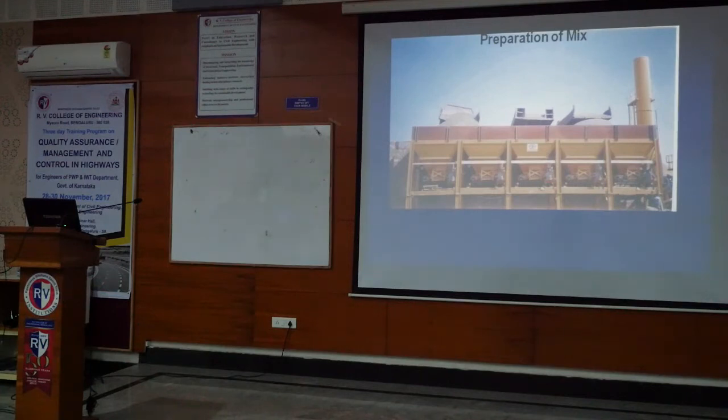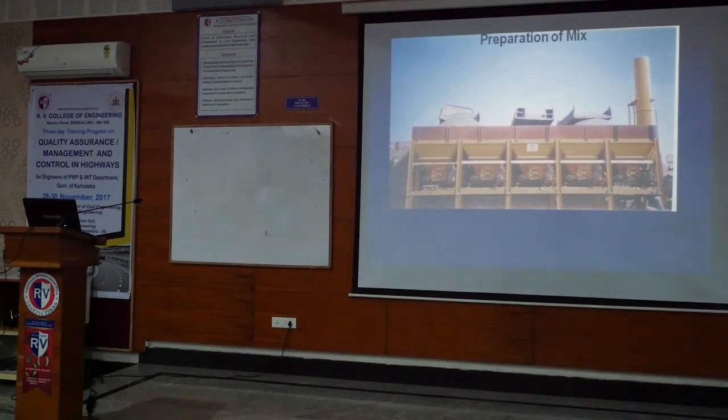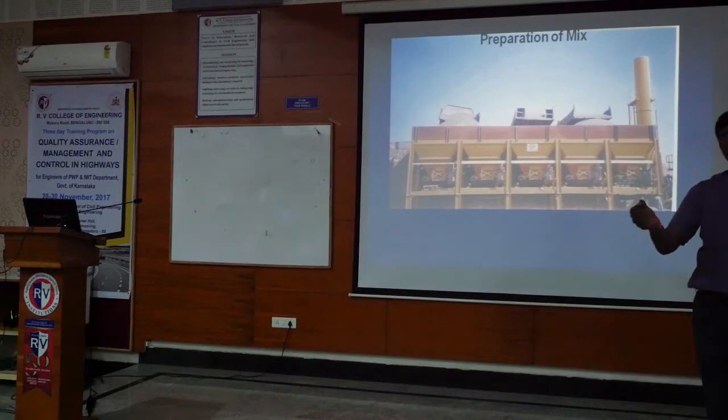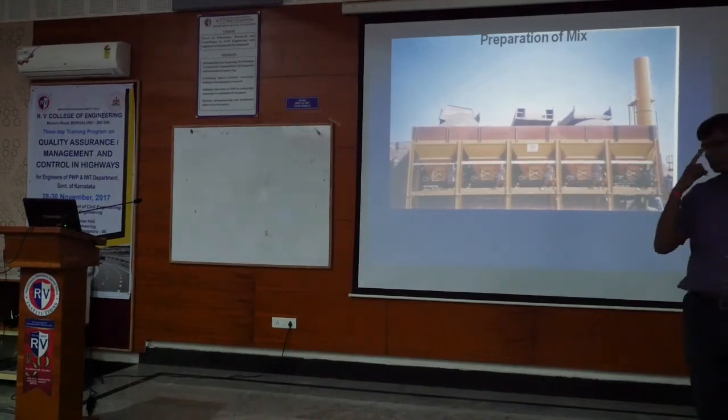End of the day, whatever name you give for the bituminous mix, nothing much is changing. Either we are changing the gradation of the aggregates and making a small variation in the binder content. Between DBM and BC there is not much difference in binder content, about half a percent. Or between BM and BC there is 1-2%.